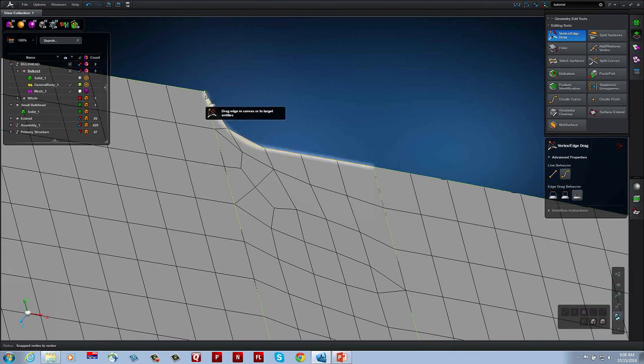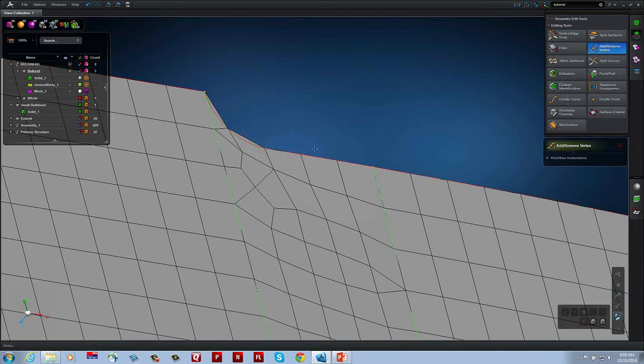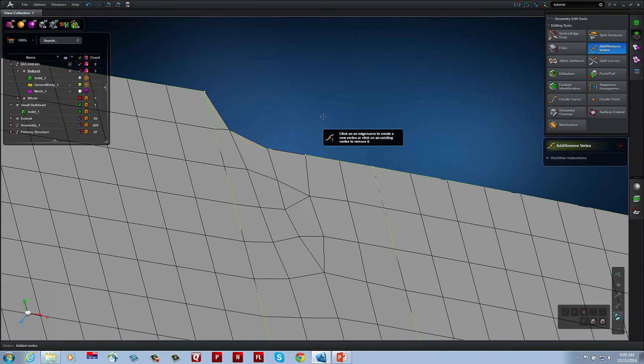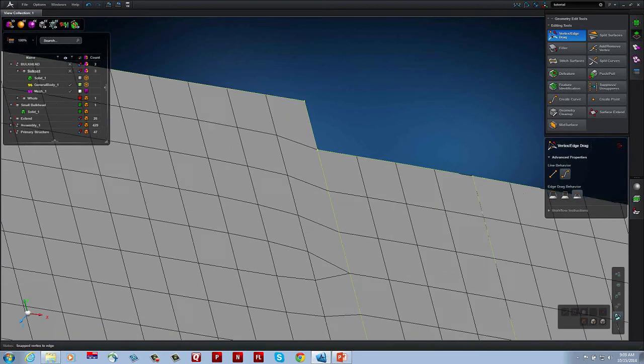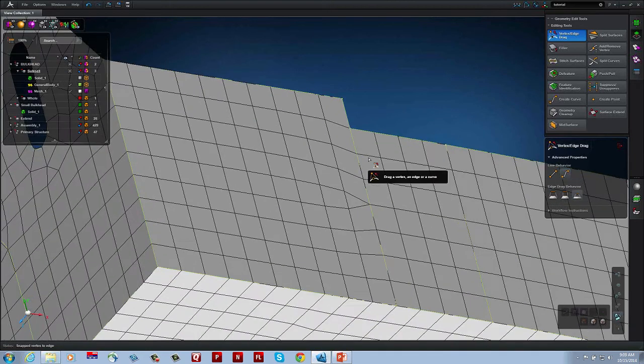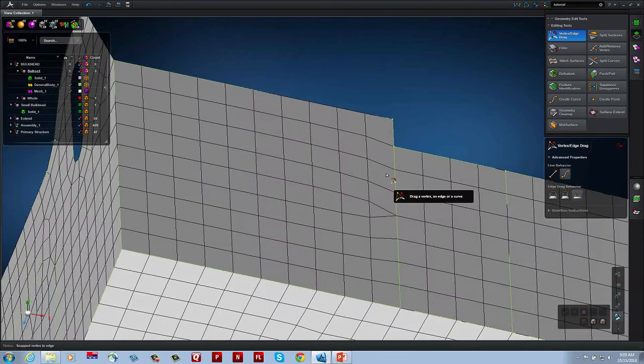I actually have what appears to be sort of a fillet. It's not really a fillet. It's really just a long edge that's got a crook in it. So let's actually fix that, and let's do some simplification. So I'm going to add a vertex there. By adding that vertex, I can now move that vertex. And I'll move that vertex over to here. I'll look at my guideline, and presto, I've squared that off now. I got rid of a detail that I may not need in my analysis.